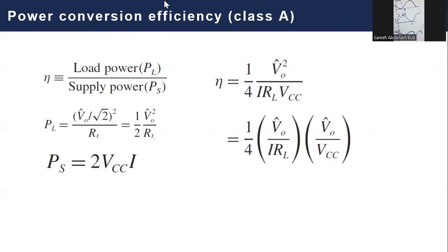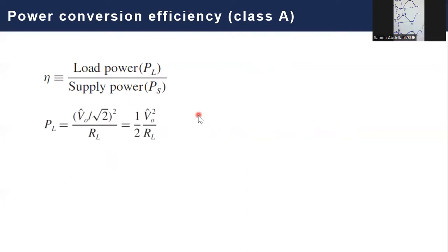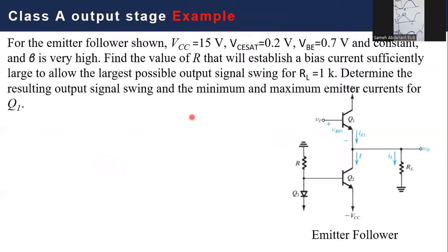Before leaving this class A and terminating this part, it's very important for you, my dear students, to investigate a very important point, which is that we implemented these power stage amplifiers seeking first a minimum output resistance. So when you build this circuit using your Multisim or your Cadence in the project, please try to investigate what is the value of the output resistance of this structure so that you can verify, is it really useful as an output stage power amplifier or not?